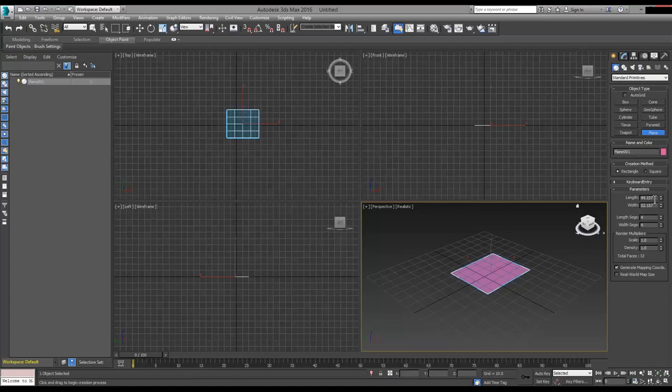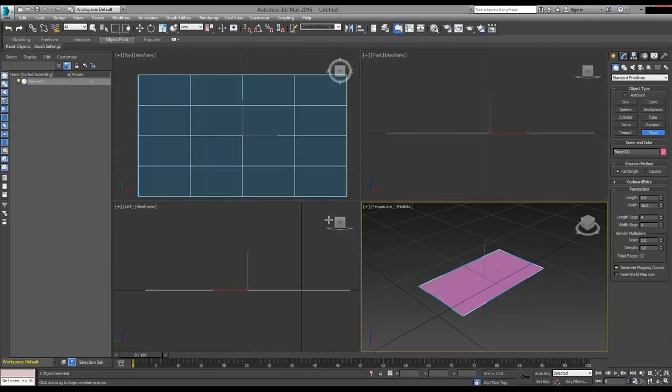And as I have a 16:9 screen, my horizontal generic units is 16, and the length in here should then be 9. So now you already see that it's a little smaller. A nice trick to get a nice view in here: I've selected the object currently, and if I click the button down here, Zoom Extents All, I see those viewports and my object in here.